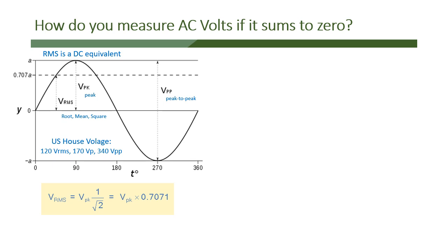But if you put your meter on that, it's going to read 120 volts root mean square, RMS. And so that's something you need to know about, that there's something called root mean square. The maximum positive excursion of the sine wave is called peak, voltage at peak. And the full span of the sine wave from the positive to the trough, with the trough being the absolute value taken of that value, is peak to peak.